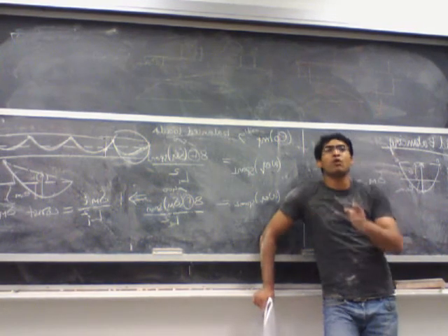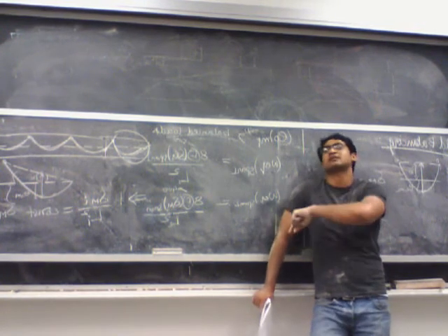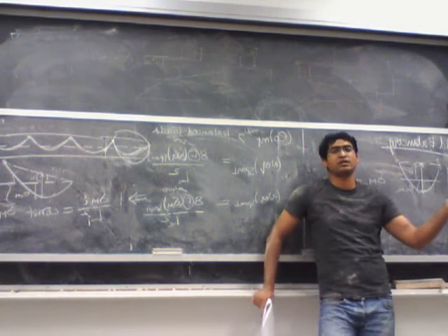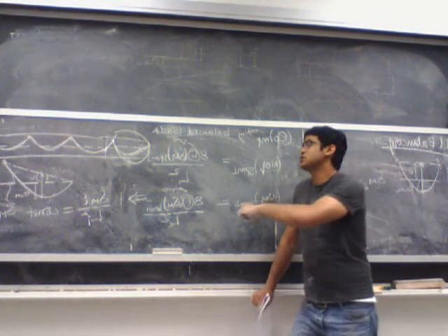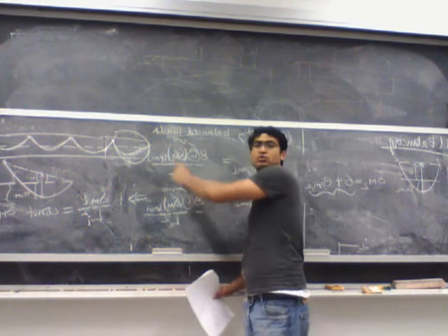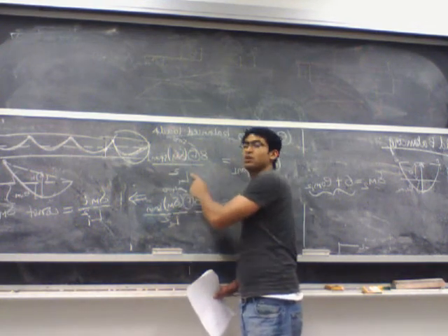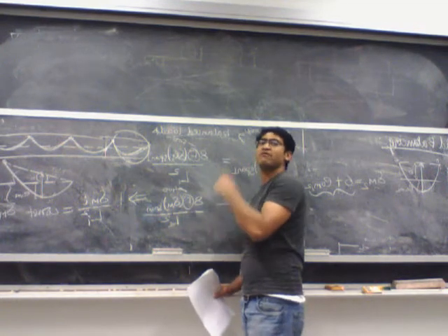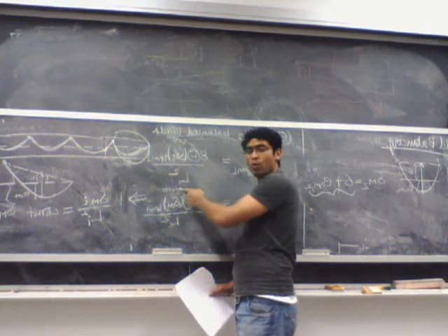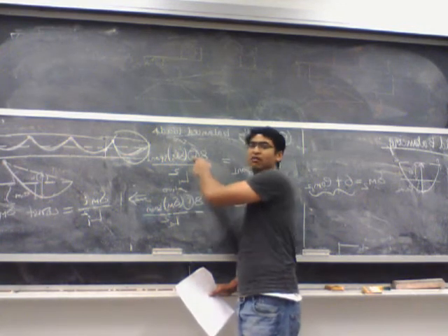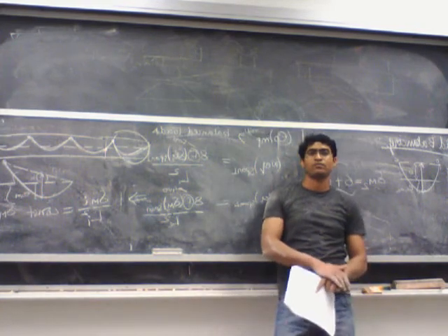The minimum will only satisfy the one span from which it is calculated. It won't satisfy any other span. So if you look at the solution, I just compared these two, the delta M's. The only reason I am able to compare the delta M directly is because L1 and L2 are the same. If L1 and L2 are not the same, then either you compare delta M over L1 square, or you calculate the value of F and then just directly compare the F values.